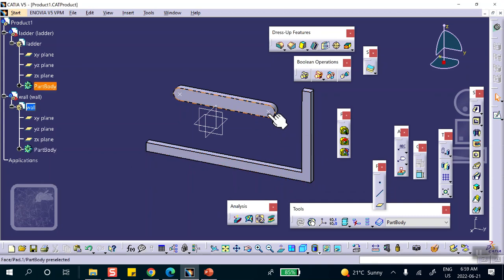Notice that this point, when the ladder is leaning against the wall, the way I've constructed it, this point is always half an inch away from the wall. And that point is always half an inch from the horizontal wall. Now, I'm not going to worry about that because I will do a slide curve joint, which is that curve at the end slides along that line. But for this point, I'm going to do a point curve joint. So I'm going to draw a straight line here, which is half an inch from the wall. And eventually I make that point always move along that line.